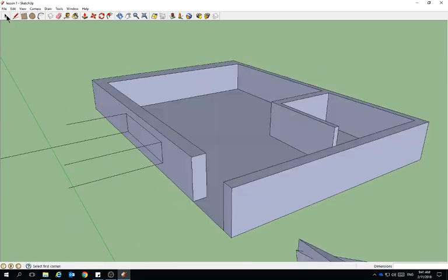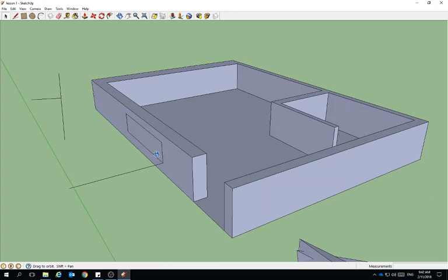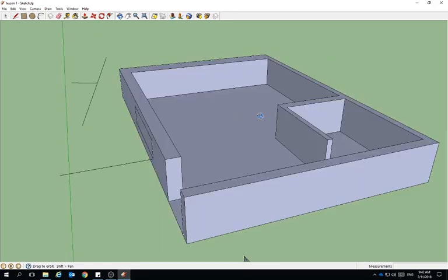Now these lines that I drew, I can now select them and I can delete them. And it's not deleting all of the line, it's deleting only the line that's coming out through the wall here. So there's a funny thing with lines, so I'll show you now. If I draw one and I use my pen or my selection tool, it selects the whole thing. But as soon as I draw another line that touches that line, and then I use my selection tool, it'll treat those ends of the line as being completely separate things. And that's what's going to happen here. I'm deleting the outside, but the inside bit of the line between this rectangle and this rectangle still exists. We just can't see it at the moment.